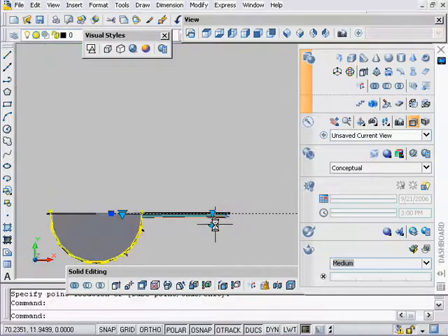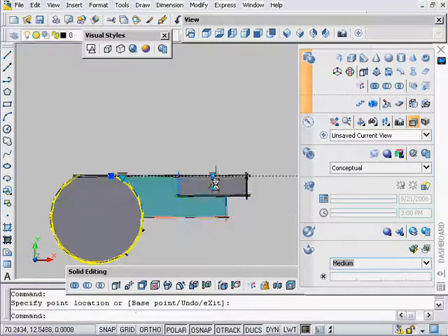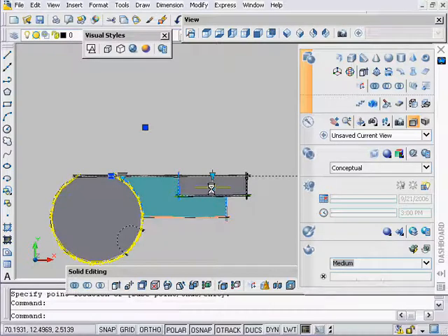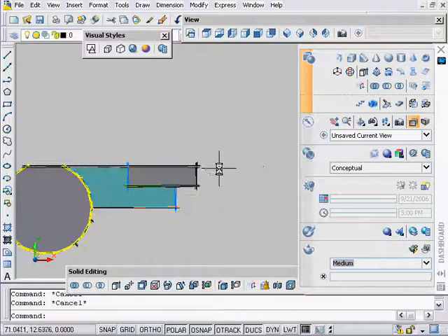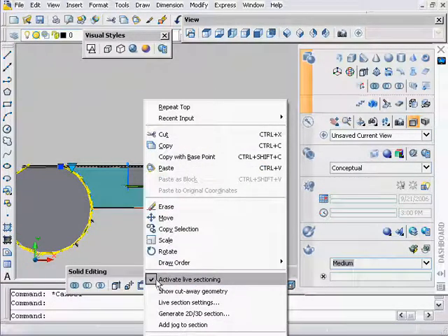Okay, and then I can flip it using my flip key here to flip it from side to side of that section plane. Okay, the other thing I should note, hover over it, click on your section plane, right click. It says activate live sectioning. Okay, look at these